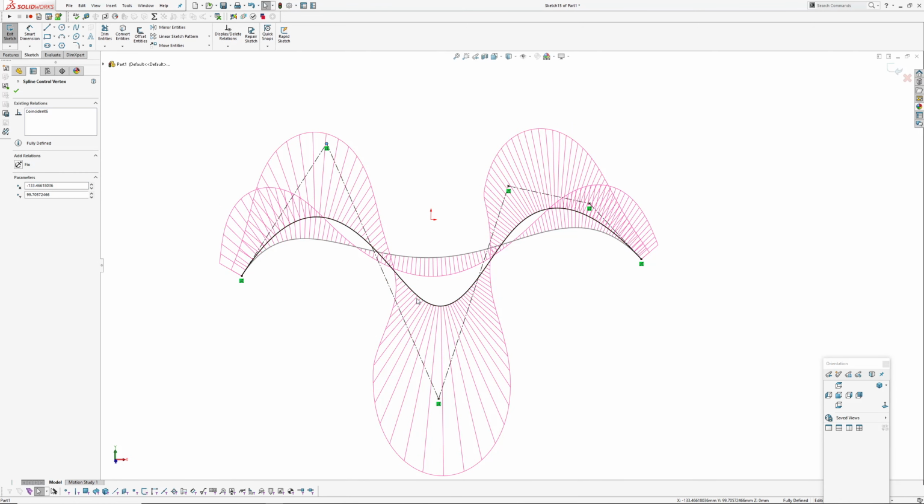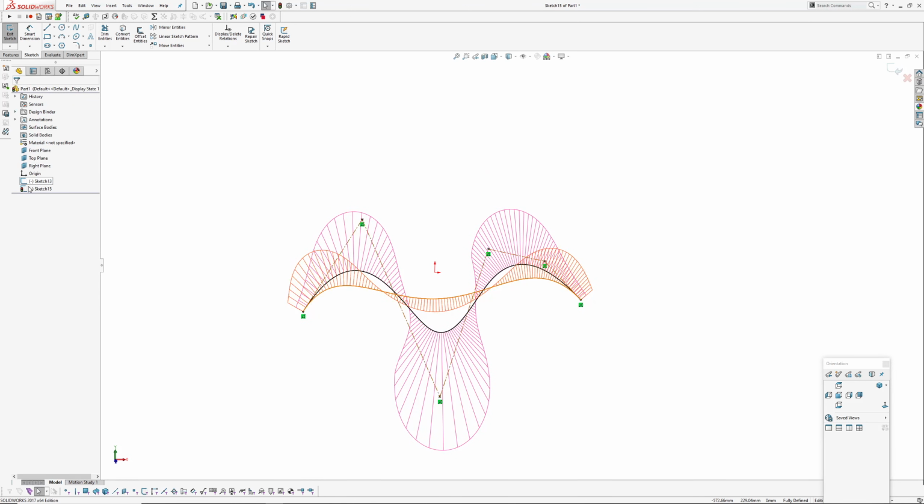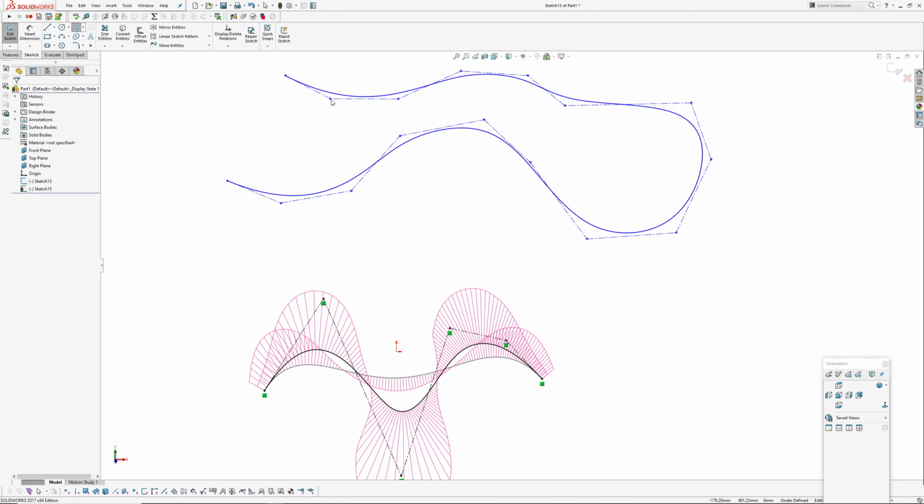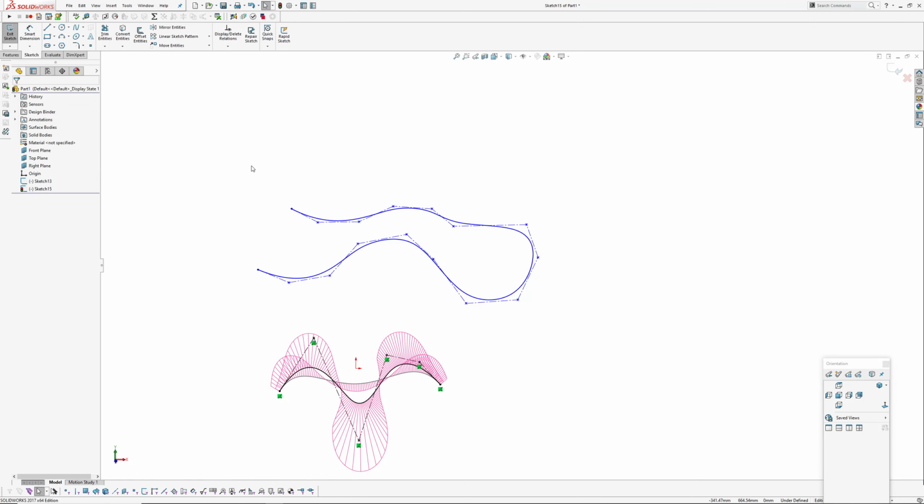Each control point has more effect on the curve. So the higher the degree in a single span curve, each point has less effect on the shape of the curve. But in, say, a degree 3 B-spline, you can bang out lots of points like this, and nothing over here has any effect on the back end of the curve here. Whereas if I was to make that as a single span Bezier,